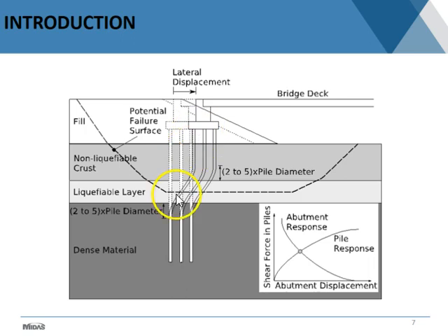That is, the piles not only work in the vertical way, the more usual one, or supporting lateral loads coming from the upper structure, but in this case, they're also helping in trying to stabilize this slope that is formed here at the bottom. The figure that you see here at the right bottom is a simplified method that was proposed a number of years ago and that has been analyzed after that, where if you look at this problem in a very simplified way, you can think of it as two separate problems that are somehow connected.